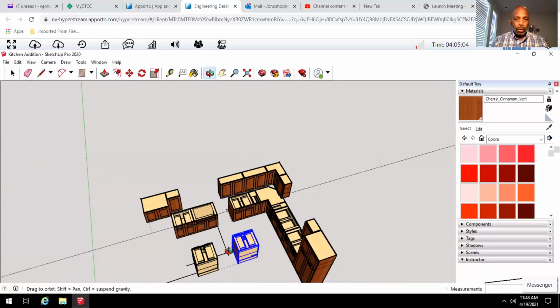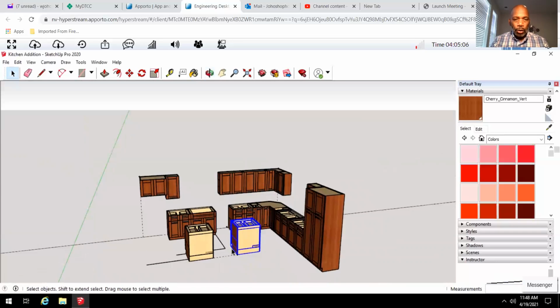So now, I don't want to see the back of these base cabinets. I have several options: the craft-made mix and in panel that most of you have used. Another option that I didn't talk about is that you could put a stud wall with drywall behind it. I think one person has found some bookcases that they're putting in the rear of these base cabinets to cover up the back side of the cabinets and the range.